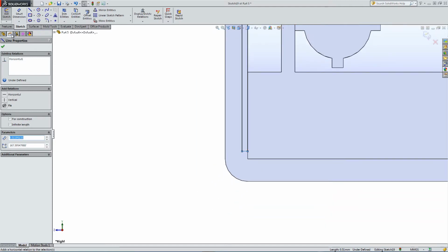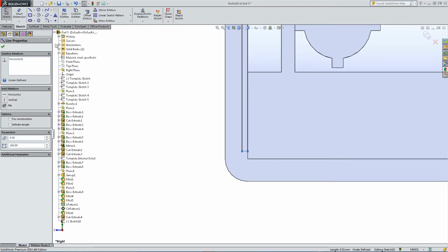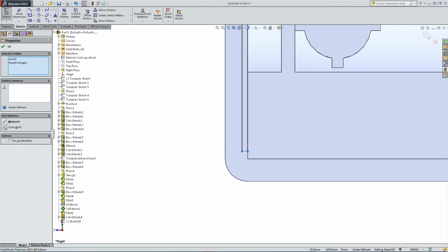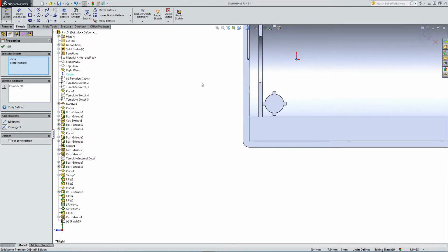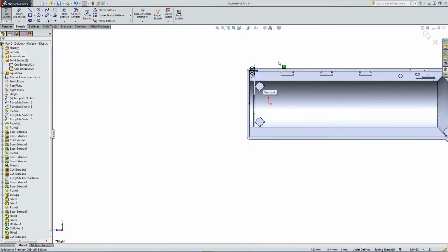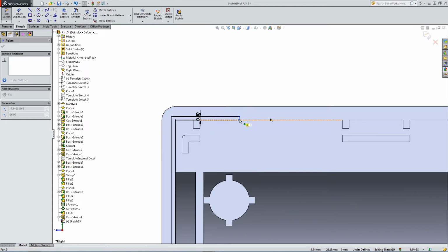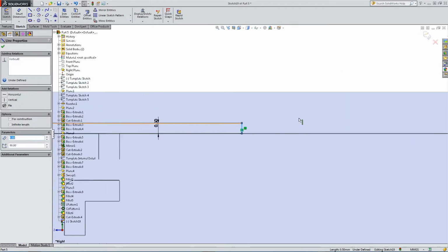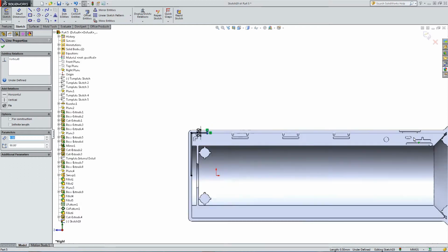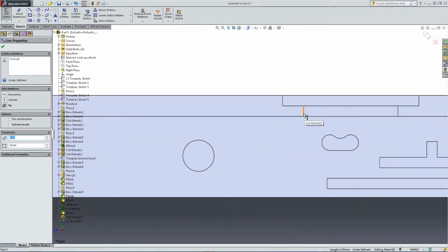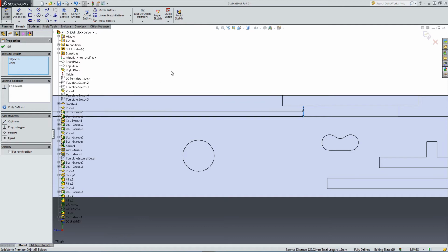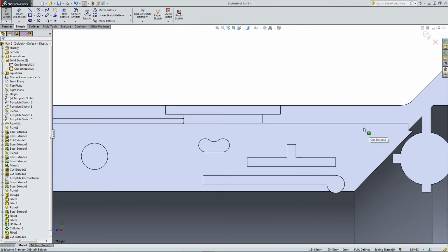I'm going to bring this back to my center line. So coincidence, and that brings me all the way back to the center, setting a coincidence mate. Not even a mate really, it's kind of a relation. So linking, adding relations. So I'm producing my interlocking geometry here.